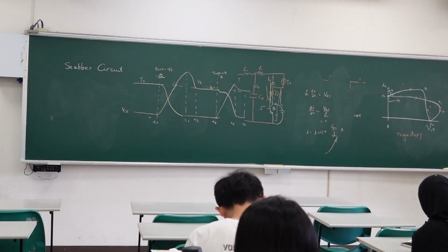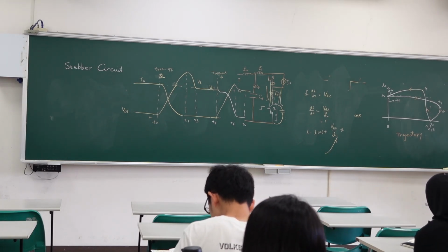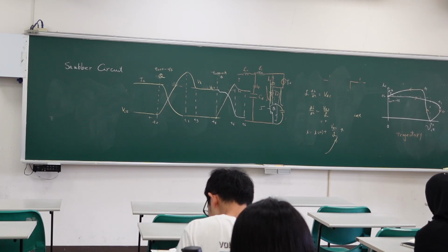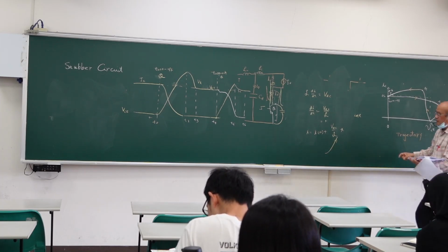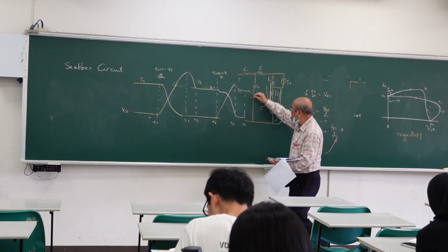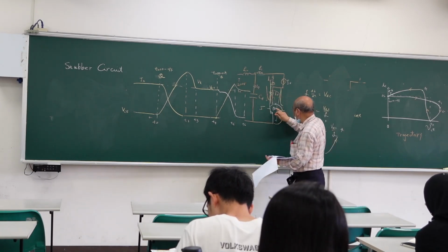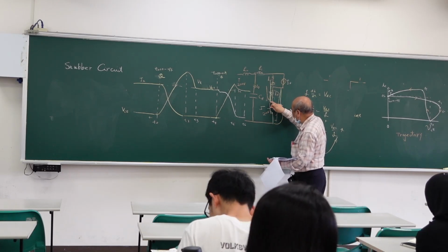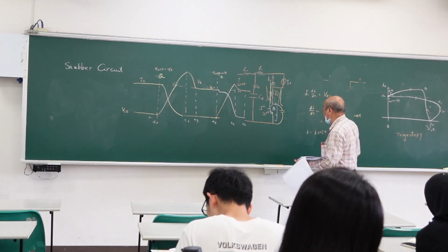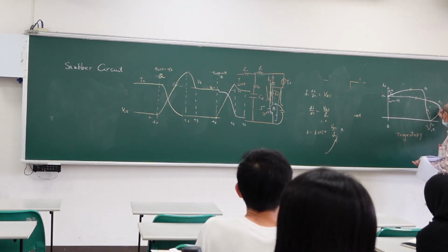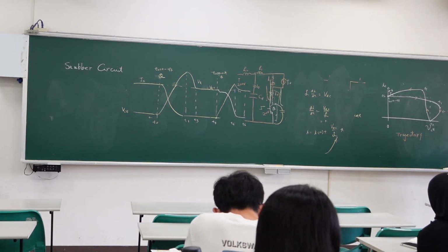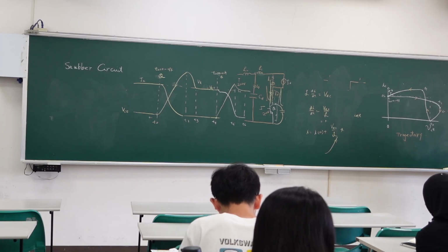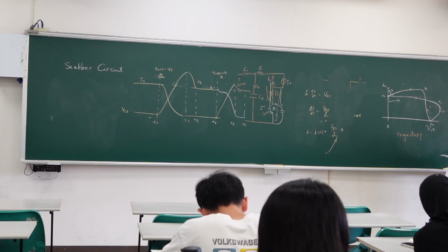So we can understand we have this trajectory. The voltage does not only reach VDC, VCE, it is more than VCE. So if you select the voltage stress, if this is 200 volt, then you cannot choose 200 volt. You should choose it could be 300 volt because it is larger than VCE. So you can see here. So we have this kind of trajectory. Then we have to consider this situation.